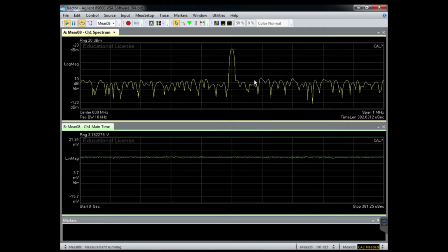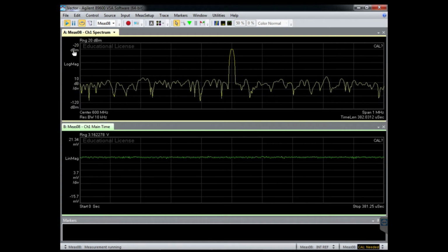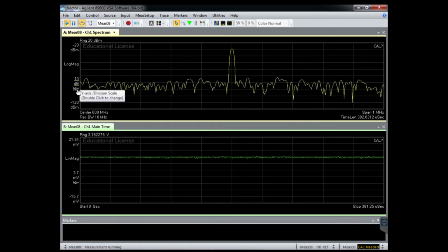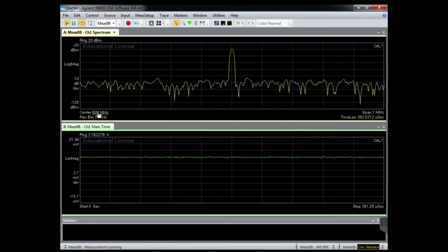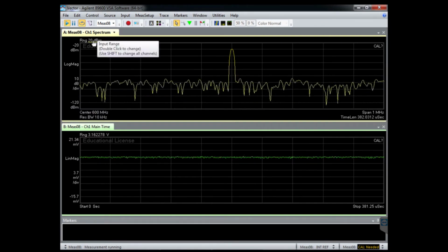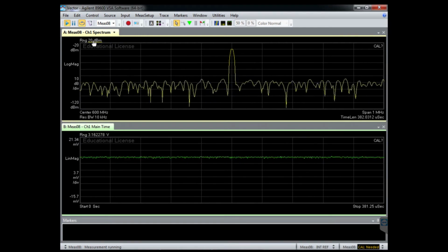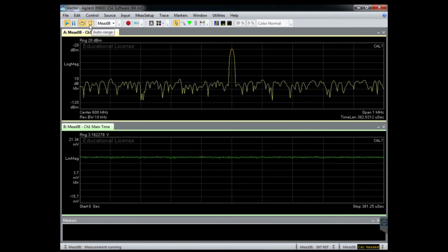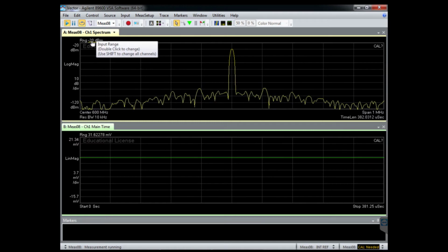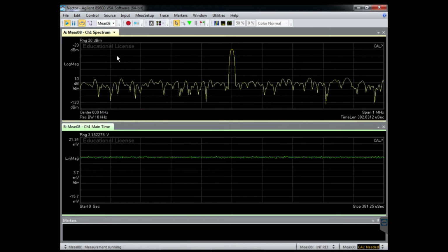Also we can do scaling for the y-axis by adjusting its maximum and minimum limits and the step size in between, in a similar way to the x-axis where we adjusted the center frequency and span. Also, we have something called range or reference level, which affects the attenuation applied by the VSA on the received signal. Instead of adjusting it manually, we can go with this option, which is auto range, which will change it automatically. Let me just bring it back to its original value.